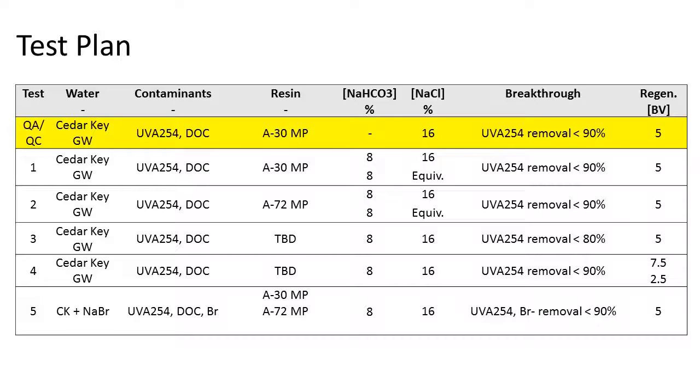A high level of sodium chloride is like 16% of what a plant might typically use. With sodium bicarbonate, you're limited by its solubility. Its max solubility at 20 degrees C is around 8.5%, and this is trying to get to about max solubility, which takes a little bit of effort when you're making big batches of it. So this is the higher end of what a plant might use for sodium chloride. And then this would be the equivalent molar amount, which is around 6.5% sodium chloride.